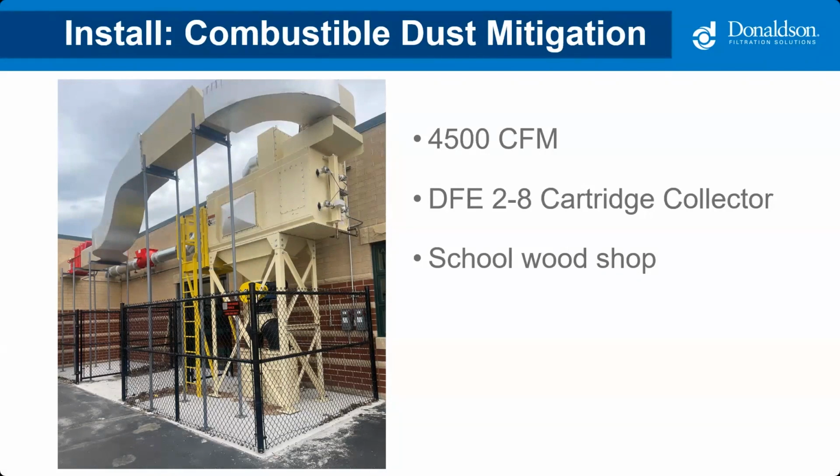You'll have more and more combustible dust mitigation practices to deal with in the industry these days. You wouldn't believe it. The only thing that's probably not combustible is rock. Everything else has a KST value and will require some type of combustible dust mitigation.